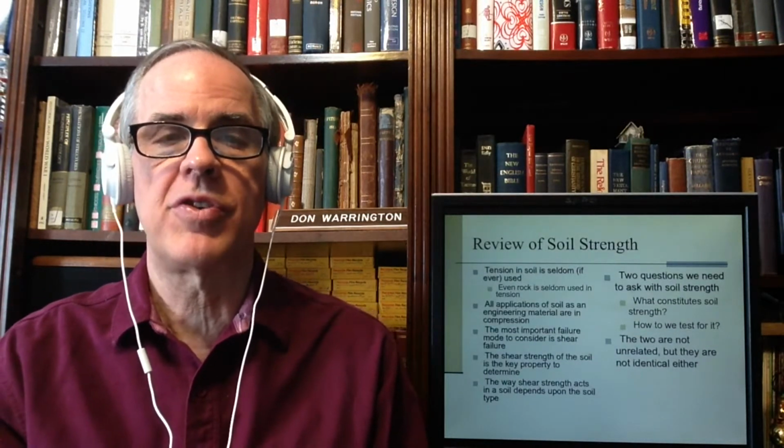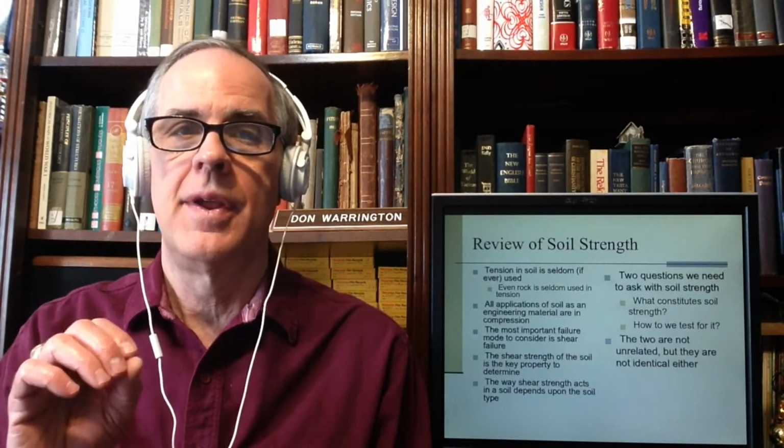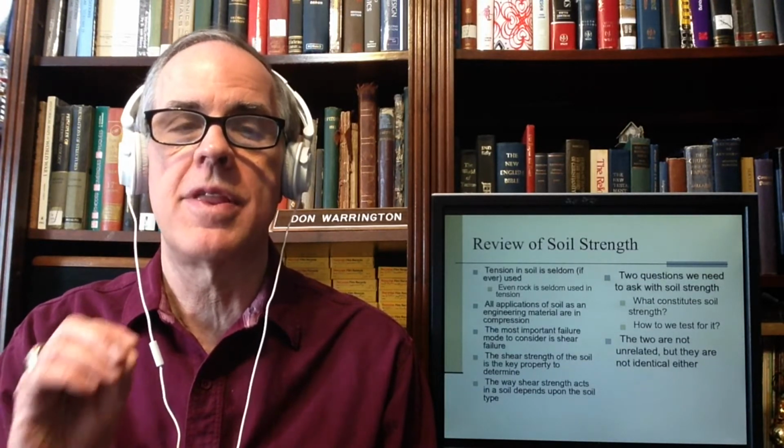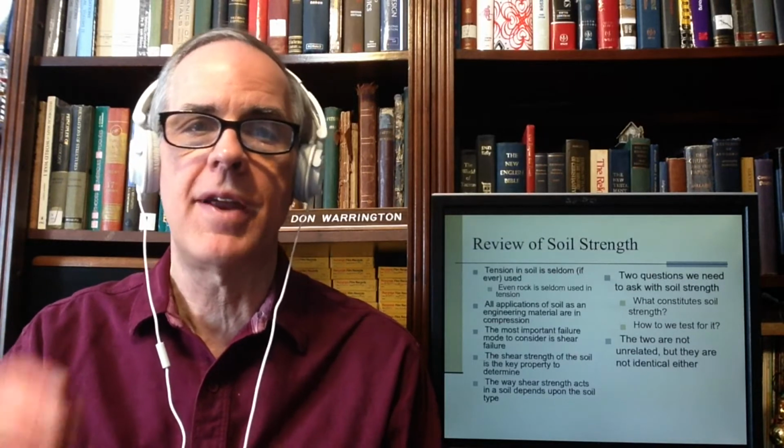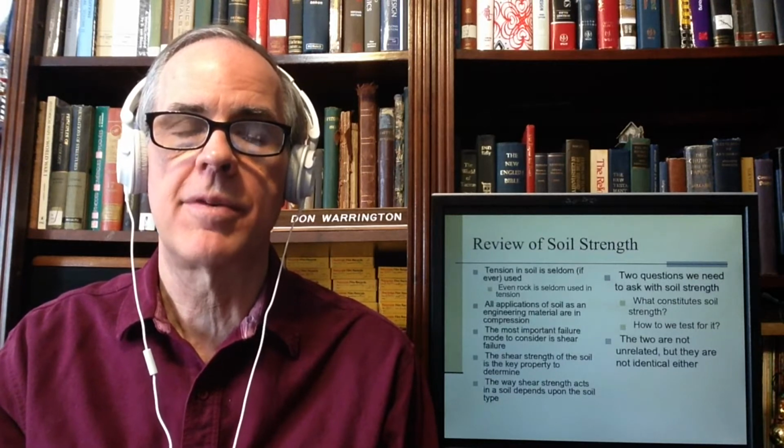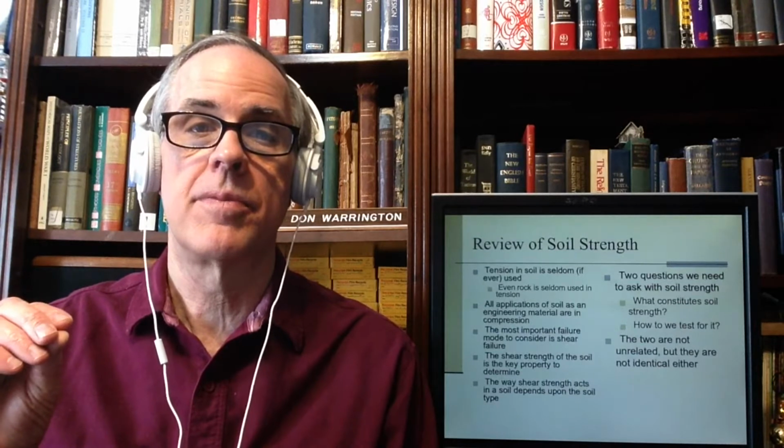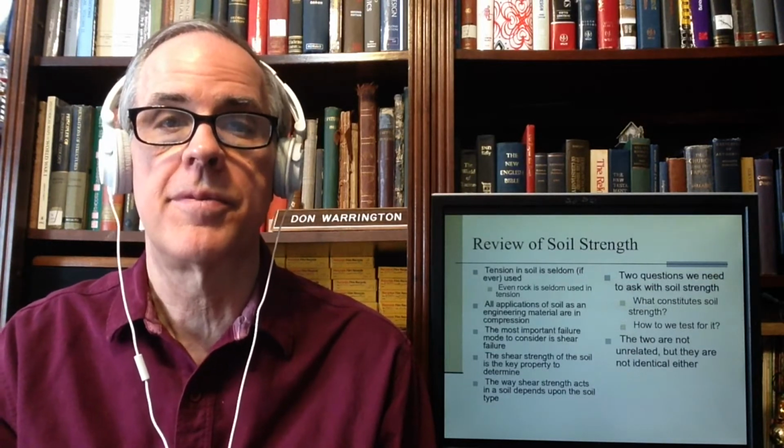One of the most common theories of failure that we use is maximum shear stress. We think in terms of tension, strength, and whatnot, but basically when we actually get down to brass tacks, the maximum shear strength failure is what we use, or to call it by its proper name, the Tresca theory.